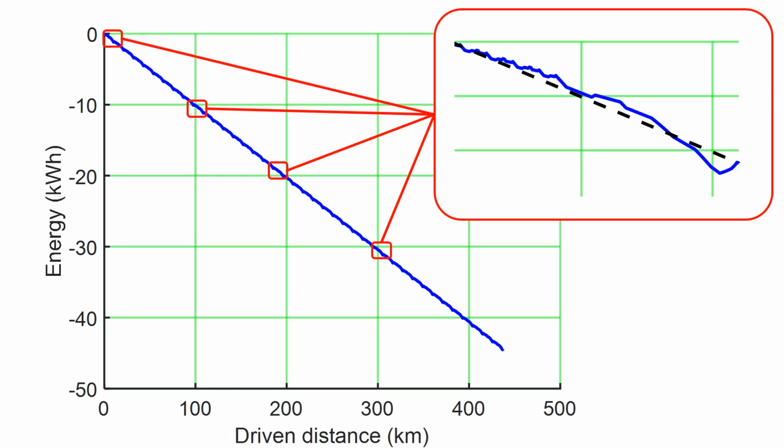We may still select to allow the battery to provide less power when it's close to fully discharged, but it is not because demanding traffic situations cannot occur at the end of a driving cycle, but rather because it's more valuable for the driver to allow the longer range than to shorten the range just because the power requirements cannot be met at low state of charge.